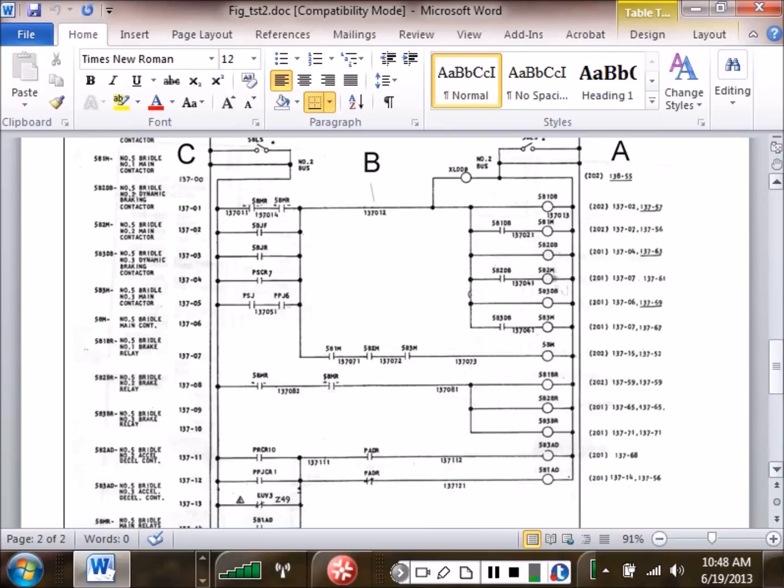So the terminal boards. By the way, the problem we get when we get into heavy industry is that all your wires are probably going to be black. So we're definitely depending on wire numbers to figure out what wire goes where, what relay is what relay, right? You understand? And of course, U.S. Steel does this on every terminal you have, which means we use a lot of stranded wire. What is that? Stranded wire over solid strand wire.